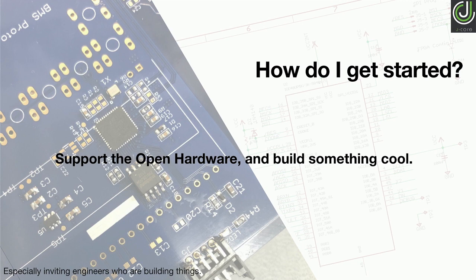So there are multiple RISC instructions that are implied by each 16-bit instruction. And so the compression that you get is more than just 16 bits out of 32. So you get probably 3 to 4 times the memory efficiency on the instruction side of the CPU than you would get with a RISC-V or with anything that's similar to that. Does that help?